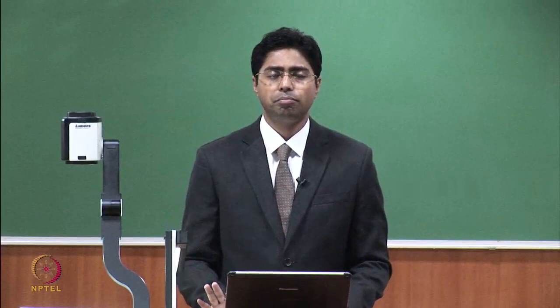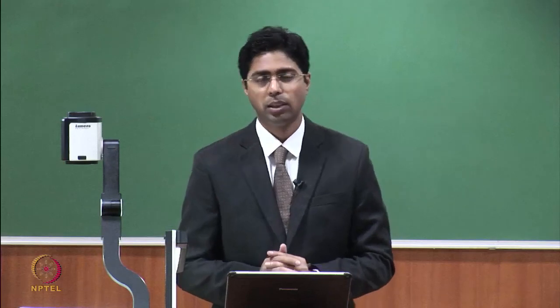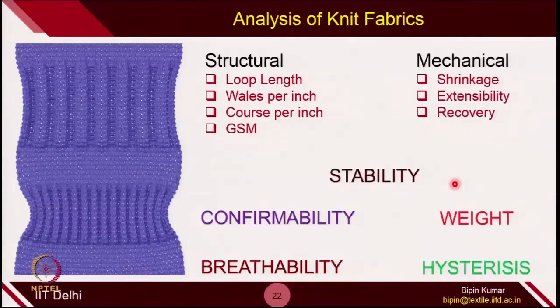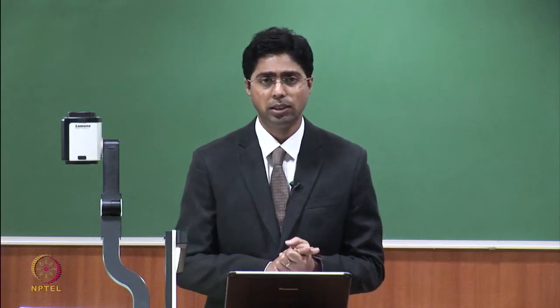In coming weeks we will go into even more complicated designs of knitting. Whatever designs you have seen so far are just the simplest ones, which are quite popular in the market, but apart from that there are many other designs like cable design, pointelle design. You have many other possibilities in knitting. Apart from that, we will also learn a new kind of knitting process where you can individually select needles of each bed. Also we will learn about some new techniques like racking of the bed, through which you can design even more complicated loop structures.